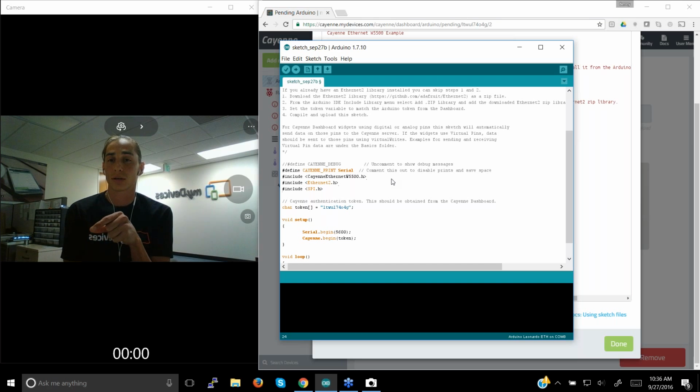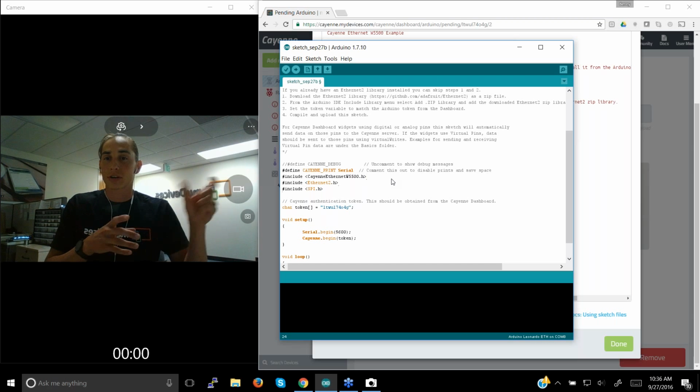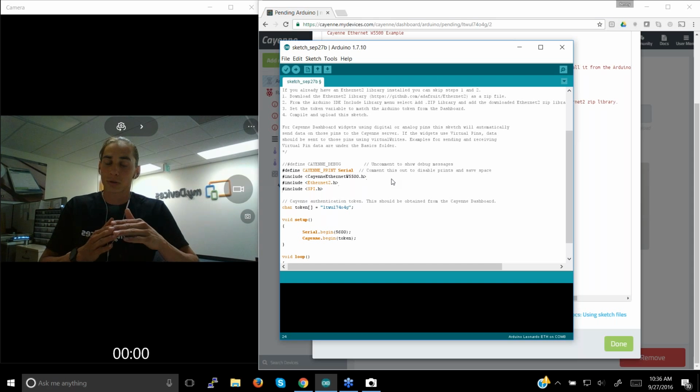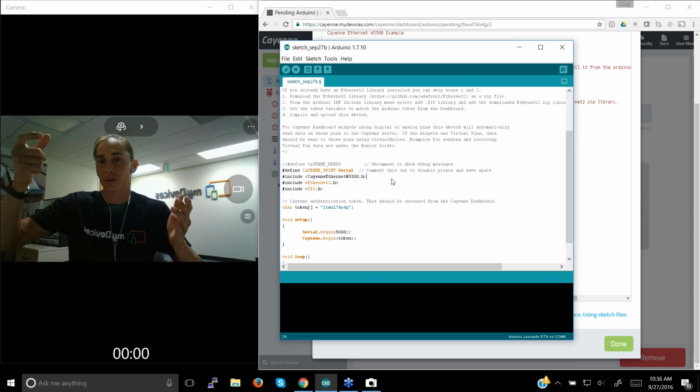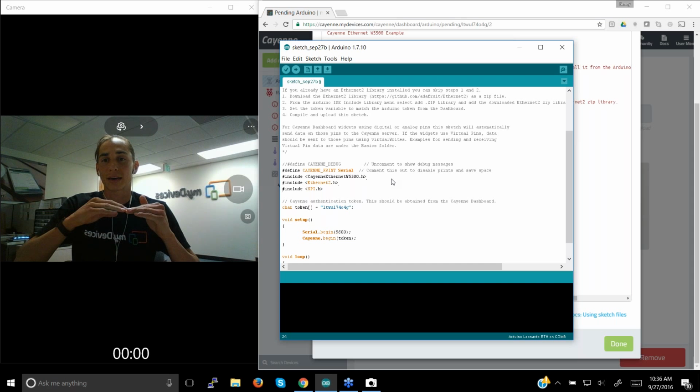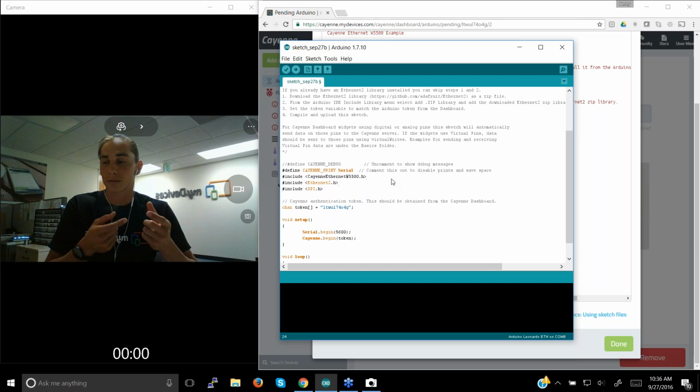Now, what if the Pi somehow restarts? If the Pi restarts, then the trigger will function as normal. Though I imagine if the temperature was at 79.8 and the Pi restarted, and while it was restarting the temperature went above 80 but then dropped below 80, when the Pi came back online, that device would never have known the temperature was above 80, because it wasn't alive.